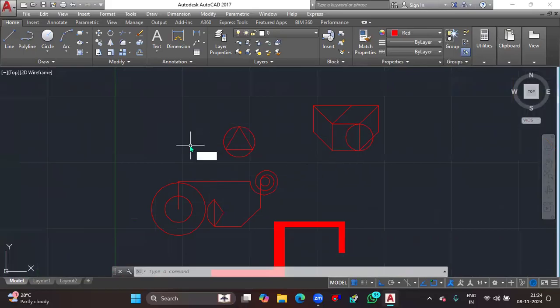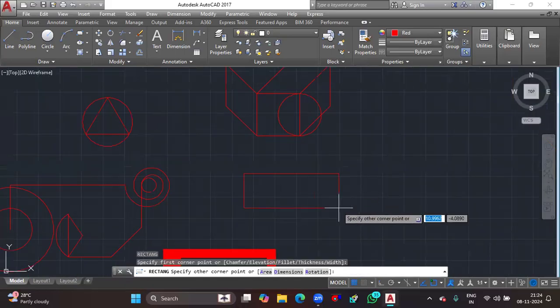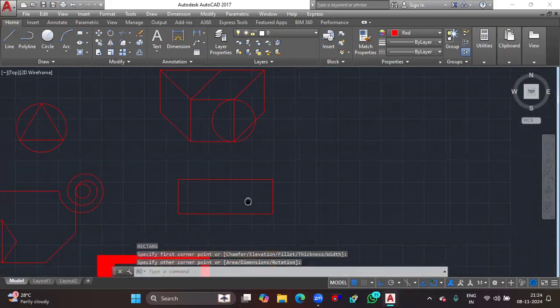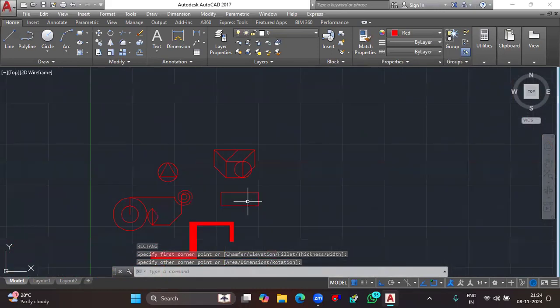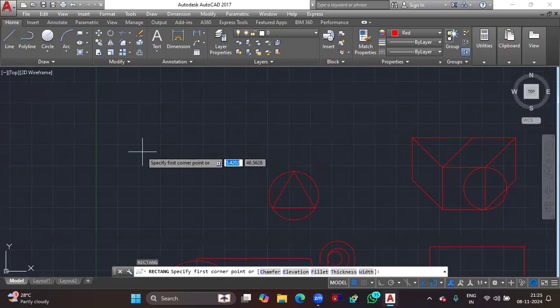Later, let's talk about the rectangle command, which is REC. It's very simple. Drag it down and you'll get a random rectangle. But the problem is not this. Your client will provide some kind of data for that rectangle, for example, dimensions. Here, I need to draw a rectangle of 50 cross 100. Sorry, that's a huge value. I'll leave it at 15 cross 10. So how to draw that?